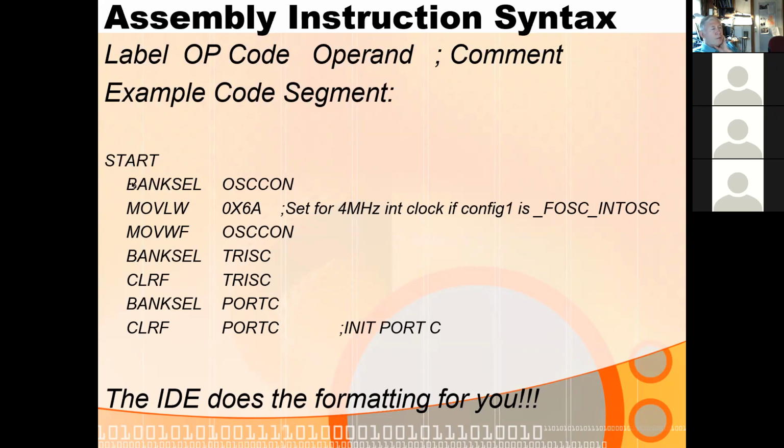Now, the banksel word itself is not an instruction, it's a compiler directive. And it tells the compiler to do something. Or again, in this case, it tells the assembly language, the assembler, to do something. We have compiler directives in C. We have assembler directives in assembler.